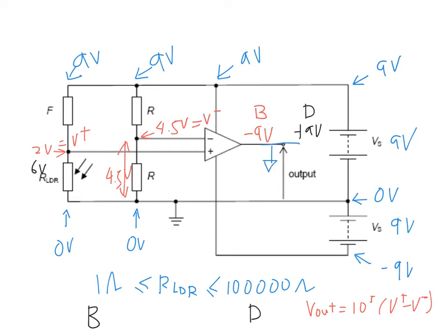So what you do, you have two LEDs. The symbol for LED is just a diode with the light shining. Now make sure you connect a resistor in series with your LED, because the LED can only take a very small current, otherwise it will spoil already. 20 milliamp, I think. Because of the very small current, you have to make sure that you put a resistor in series.